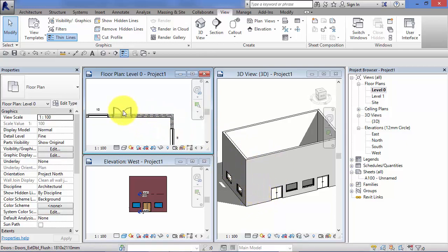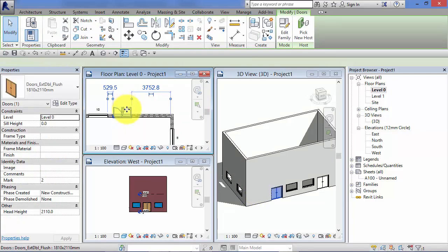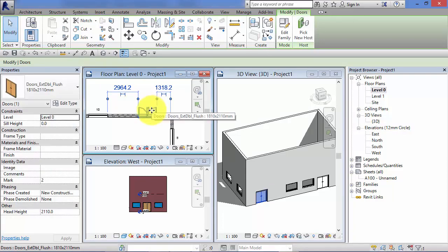Do the same with this door now. If you move this door along, hit the door up and move it, and let go. Notice how any view that references the elements that you're editing or moving gets updated in real time. So this feature makes it really efficient to work with multiple views in Revit, so you can start changing, modifying, adding to your design, and you can see the effect of those changes in multiple views virtually instantly.